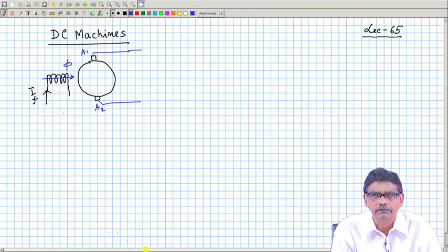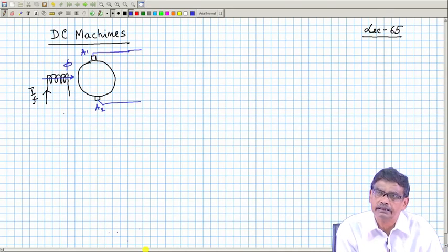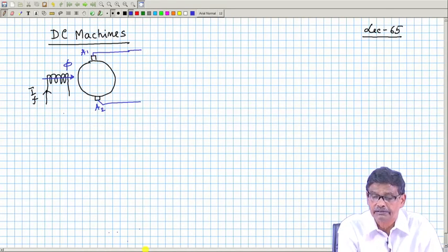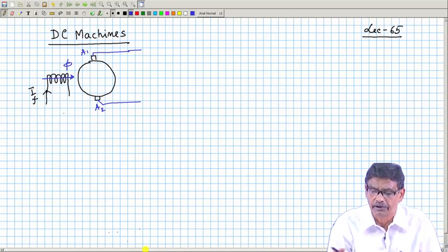With the field winding on the rotor and the armature winding on the stator, the mechanical way that we are rectifying the AC input voltage can be done with solid state switches. That is of course outside the scope of this lecture. We will consider conventional DC machines, where field winding and armature winding cannot change their places, that is, the armature cannot be on the stator and the field winding on the rotor.